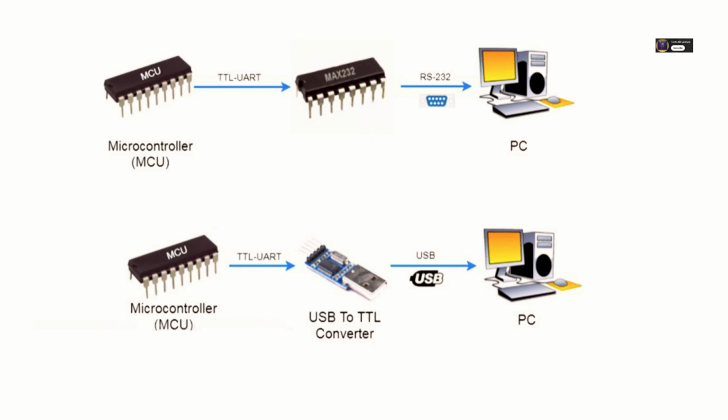Second, they handle the logic conversion. Remember, TTL logic is typically HIGH equals 1, LOW equals 0, but RS-232 is often inverted. A positive voltage means logical 0, and negative voltage means logical 1. The level shifter flips the logic appropriately. You cannot connect them directly. You'll either get no communication or worse, damage the lower voltage device.